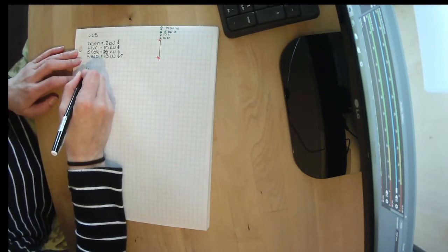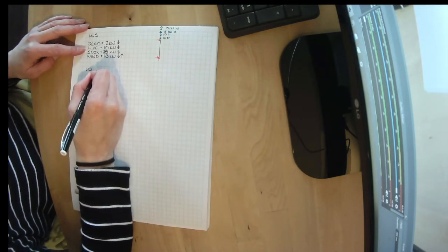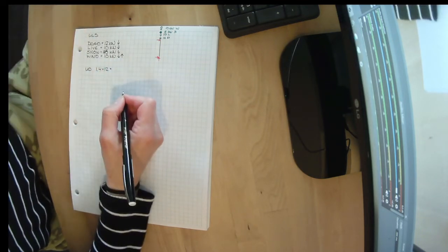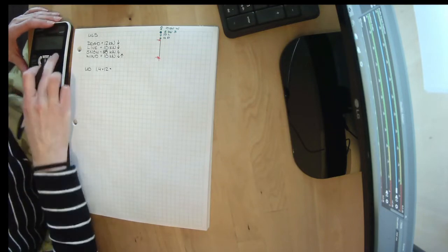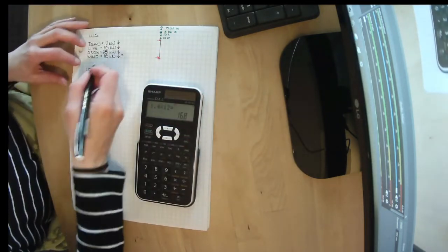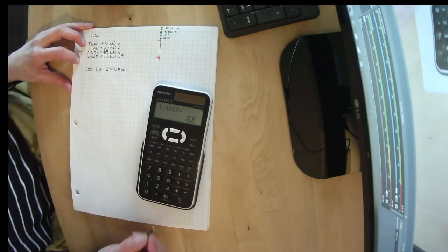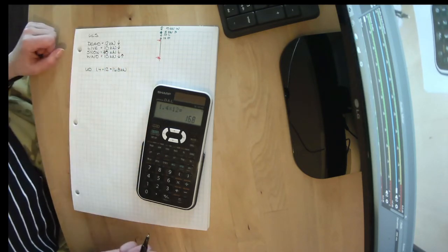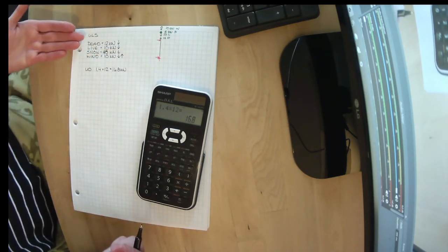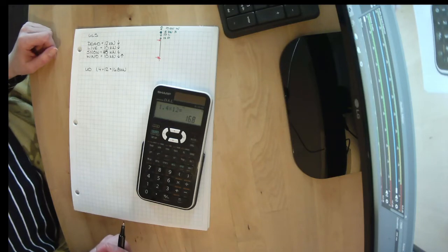Well, we know that the very first one is our dead load case, which is 1.4 times 12 kilonewtons. 1.4 times 12 gives us 16.8 kilonewtons. Great, so that is one possibility our column could see. Remember, these things don't all necessarily happen at the same time. These are all the possibilities that it could have. These are the maximum loads for each of these things we've calculated.